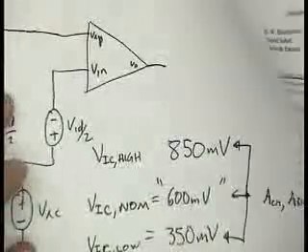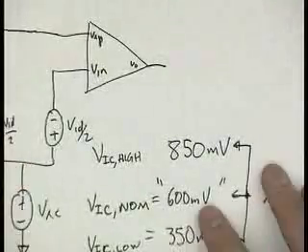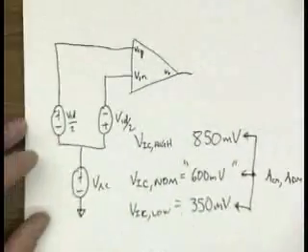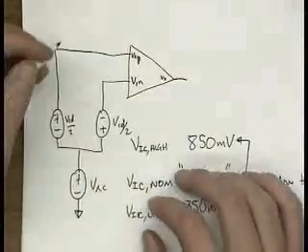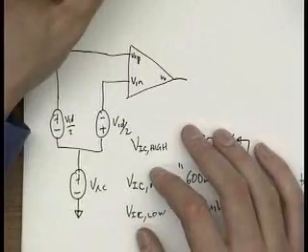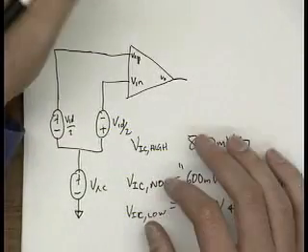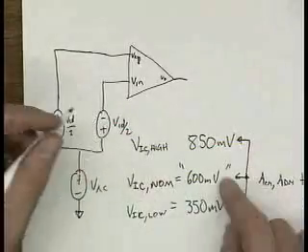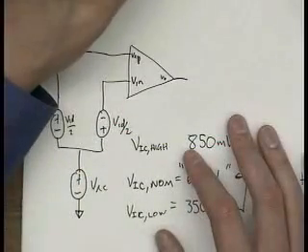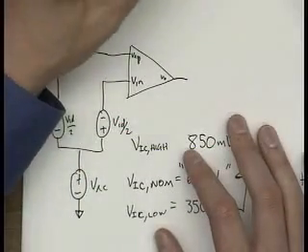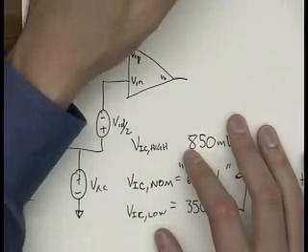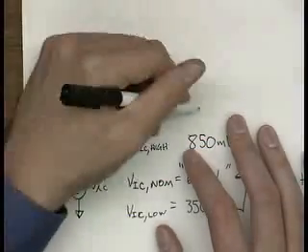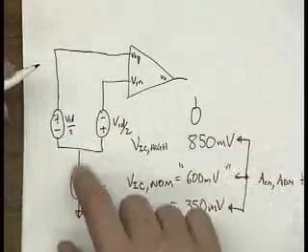Okay. And so what we do here, and you'll see this in the test benches that I'll talk about a little later, is that you do that .tf statement, which figures out the gain, and we apply this common mode, and then we do a .tf with Vout versus VID, where VID is related to here.